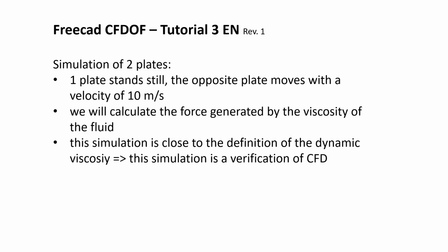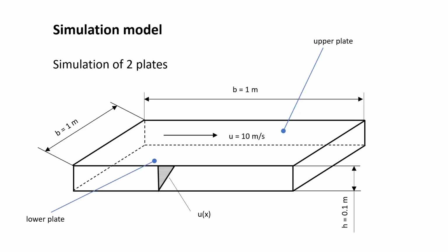One plate stands still, the opposite plate moves with a velocity of 10 meters per second. We will calculate the force generated by the viscosity of the fluid. This simulation is close to the definition of the dynamic viscosity. This means that this simulation is a verification of CFD.